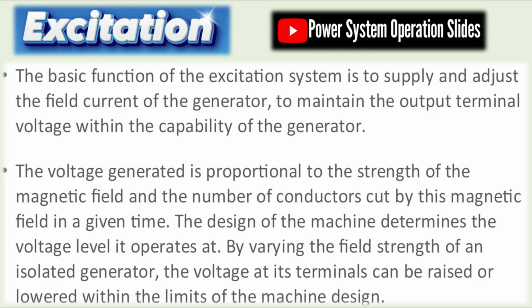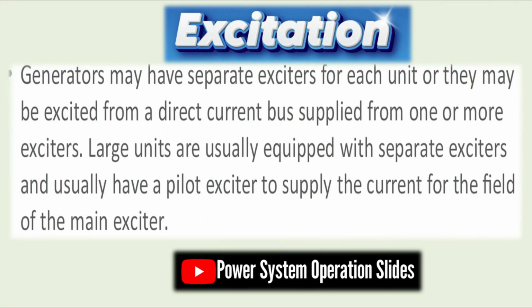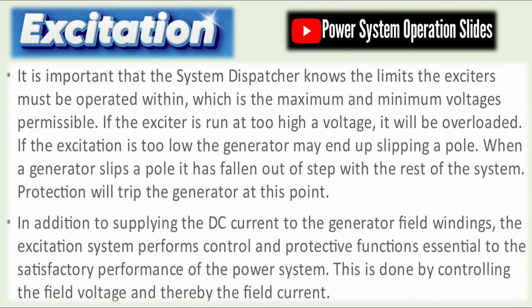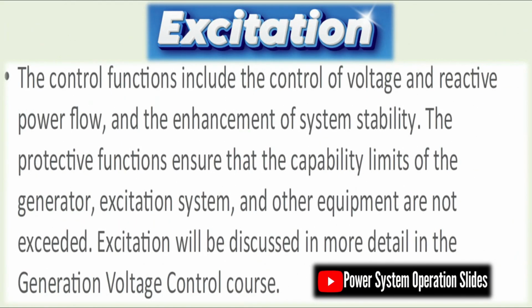In pressurized water reactors (PWRs), the primary loop heats water under pressure, preventing boiling. This transfers heat to a secondary loop via a heat exchanger steam generator. In boiling water reactors (BWRs), water boils directly in the reactor core to produce steam. Advanced reactors include fast breeder reactors, which produce more fissile material than they consume, and small modular reactors (SMRs), which offer scalable, safer solutions. Nuclear plants require strict safety systems, redundant cooling, containment buildings, emergency shutdown systems (SCRAM), and monitoring systems.